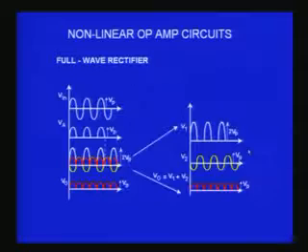So with this background, let us try to look at these various signals. You have a sinusoidal input, and the half wave rectified signal will be something like this. One half is cut off, the negative excursion, only the positive half cycles are there, and I still get V peak as the peak of this rectified signal.